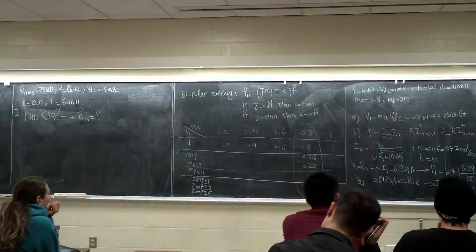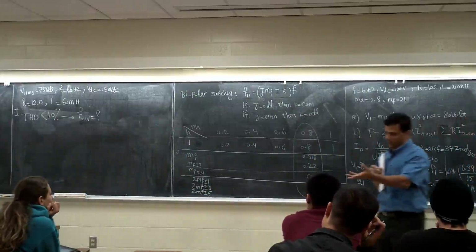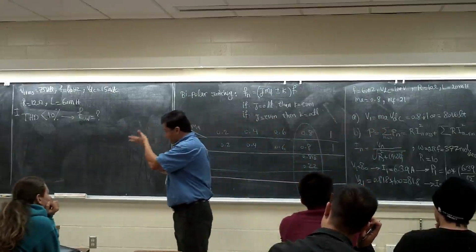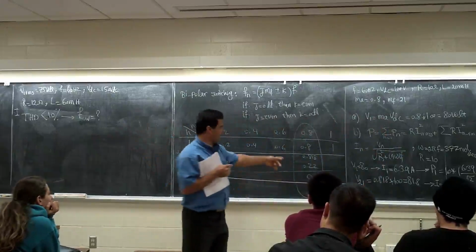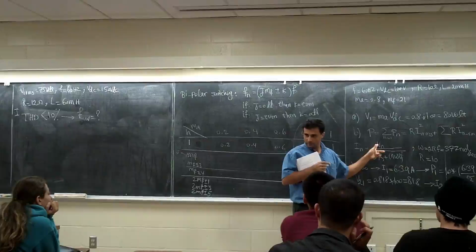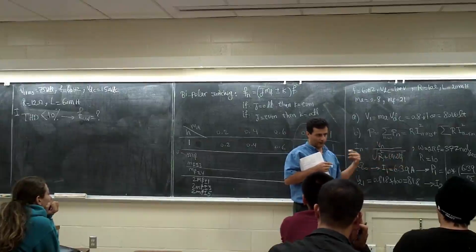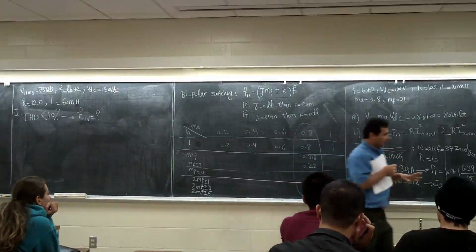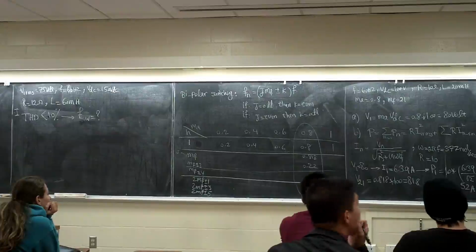I'm going to do this one. I said, okay, he gave me the first harmonic, 75 volt. I know the frequency is 60 hertz, right? What I can do, I can go calculate my I1, right? I know this one. I know R. I know N is 1 for the first one, omega, everything, right? I calculate my I1.